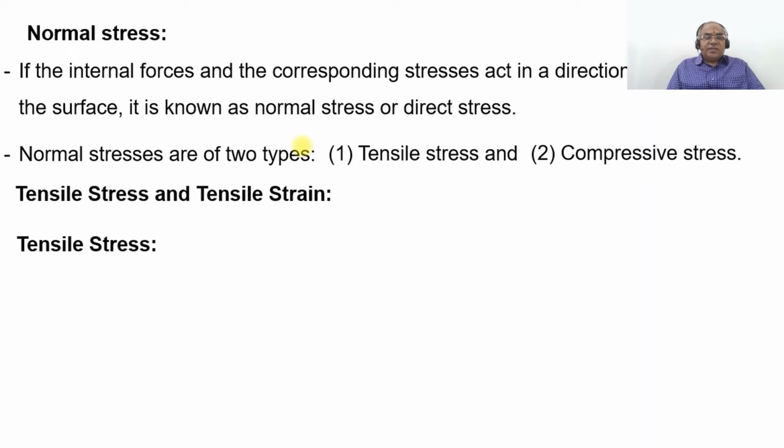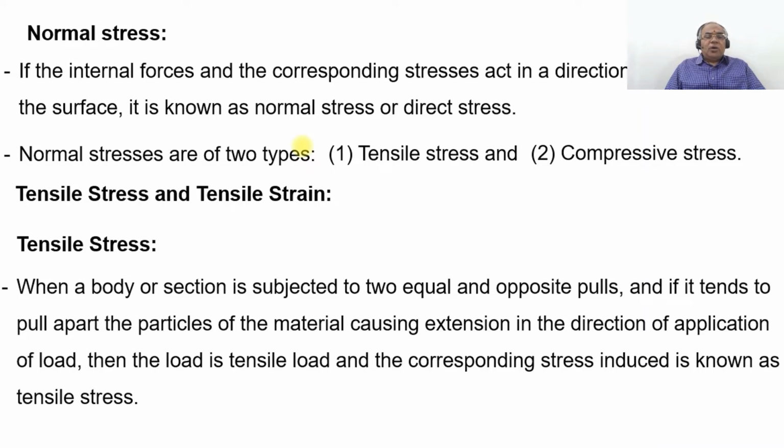So what is the tensile stress? When a body or section is subjected to two equal and opposite pulls, and it tends to pull apart the particles of the material, causing extension in the direction of application of load, then the load is a tensile load and the corresponding stress induced is known as the tensile stress.